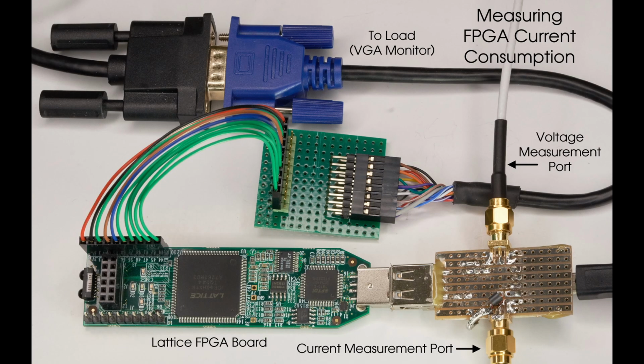I was especially keen to try this with an FPGA board because it could be extremely handy for monitoring if outputs were incorrectly driving things or even for troubleshooting by retasking a status LED. For this test, the FPGA was configured to drive a VGA monitor as an example task just to consume power, and then also simultaneously toggle an LED with 5 milliamps of load to see if that small additional load current could be detected.